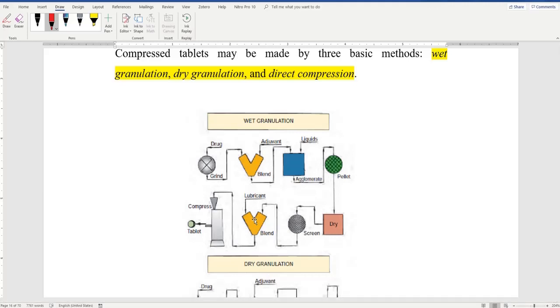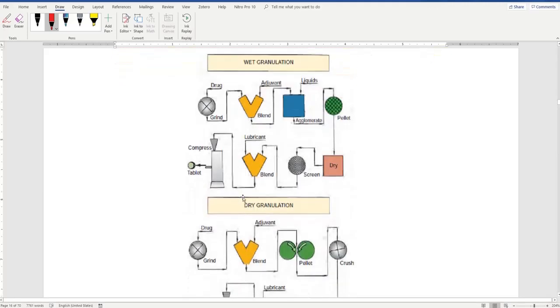I do not need the lubricant to be inside. If it is inside, then it will prevent forming the tablet, and prevent the tablet from having good mechanical strength. That's why I'm not really concerned with getting a uniform mixture in this case. So we add lubricant as the last thing in the process.